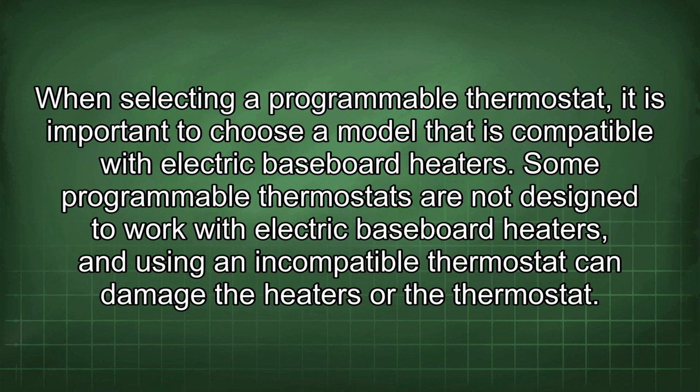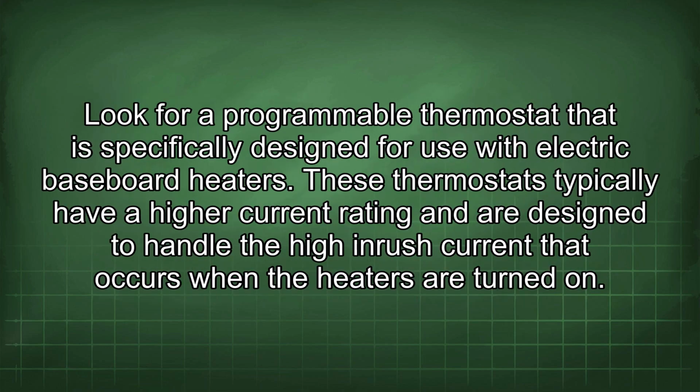When selecting a programmable thermostat, it is important to choose a model that is compatible with electric baseboard heaters. Some programmable thermostats are not designed to work with electric baseboard heaters, and using an incompatible thermostat can damage the heaters or the thermostat. Look for a programmable thermostat that is specifically designed for use with electric baseboard heaters. These thermostats typically have a high current rating and are designed to handle the high inrush current that occurs when the heaters are turned on.